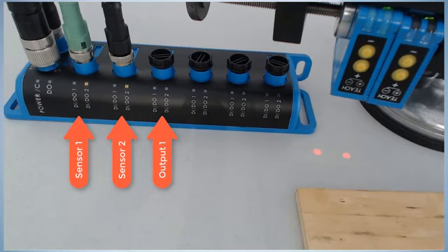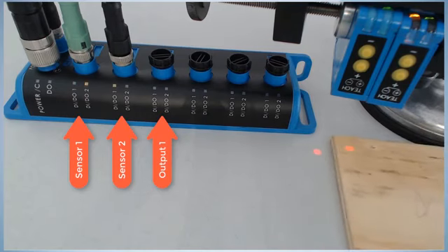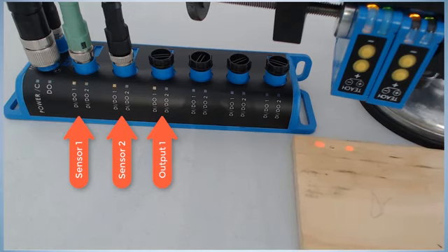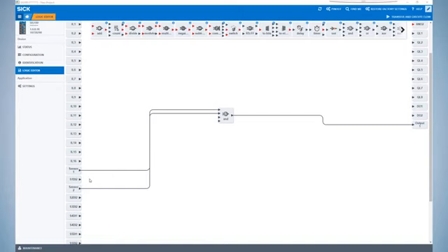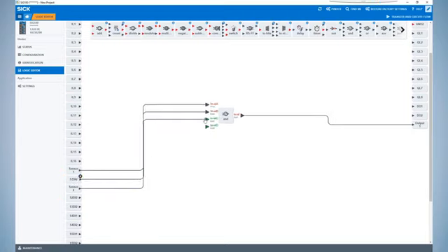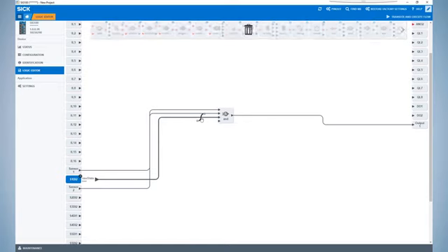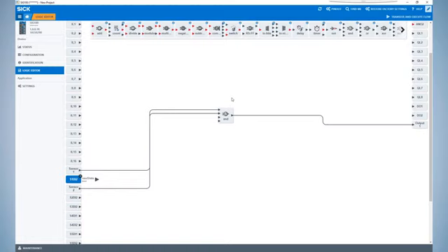Next, test your application. In this case, we observe that when both sensor 2 and sensor 1 inputs are active, output 1 will be active, as defined by the logic configuration that was just created. Remember that editing your logic configuration is simple after testing. You can add new connection lines as needed. Likewise, a connection can be deleted by dragging it to the garbage bin.